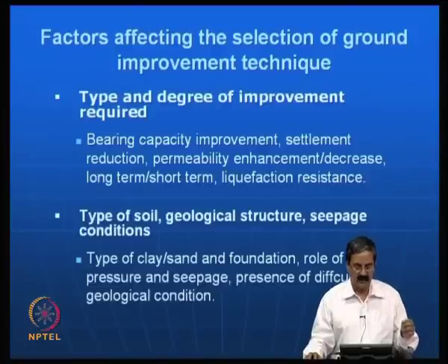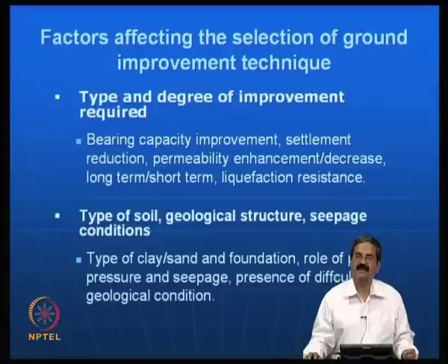So, what is long term, what is short term? This is another important point, because a soil is getting consolidated, right. I have seen in many places where you need improvement only for 1 year. That is short term. Say, for example, you start loading on a soft soil, constructing a highway embankment 3 or 4 meters high with sand that you are dumping. The rate of dumping will be so high that the soft soil area, because of its low permeability, cannot take it. So, only during that 1 year, since you are loading and constructing that embankment, you want improvement.